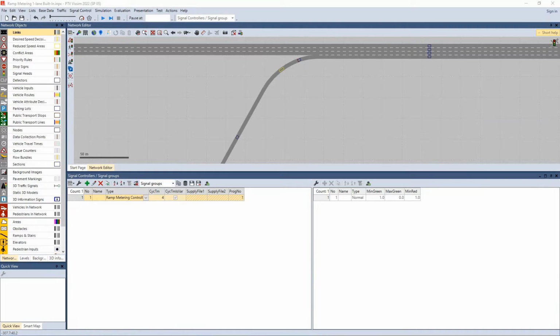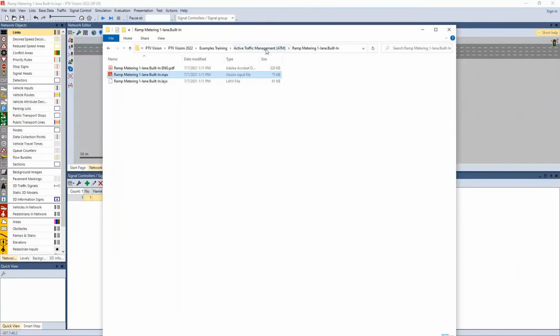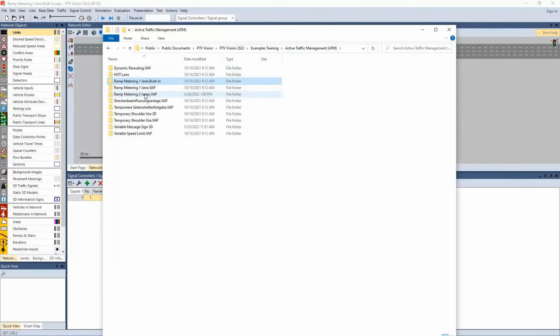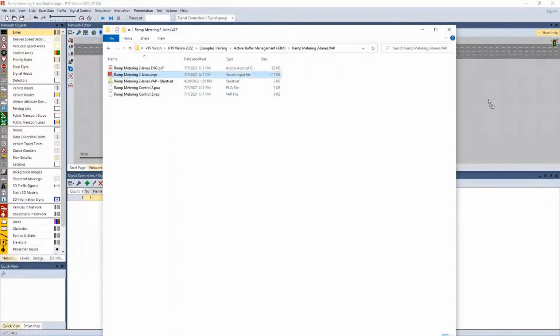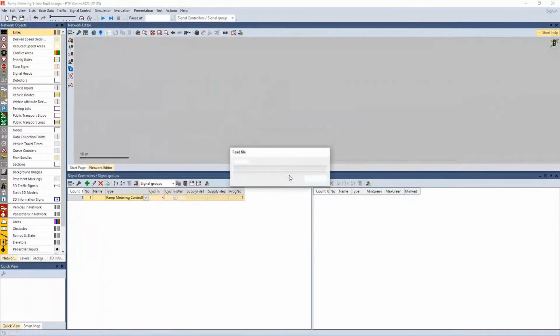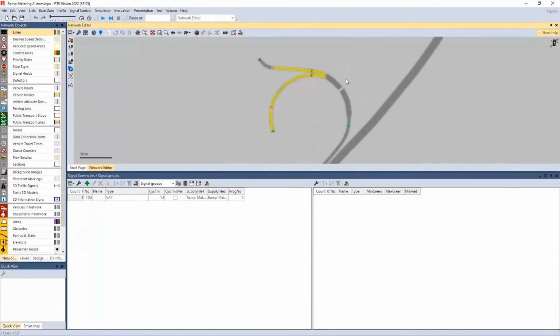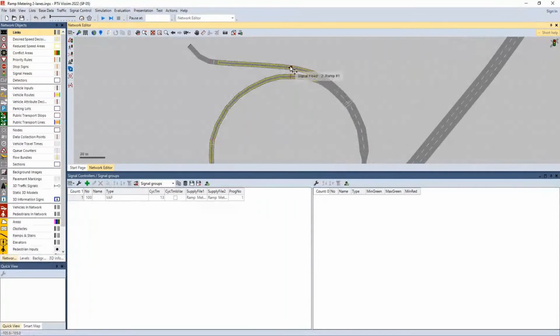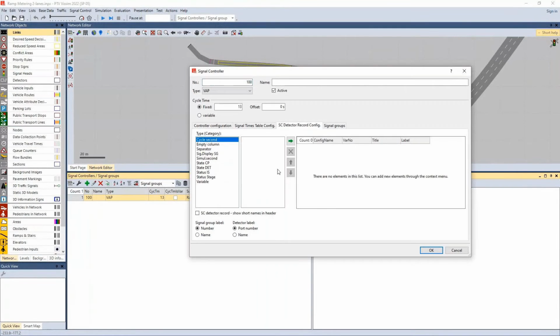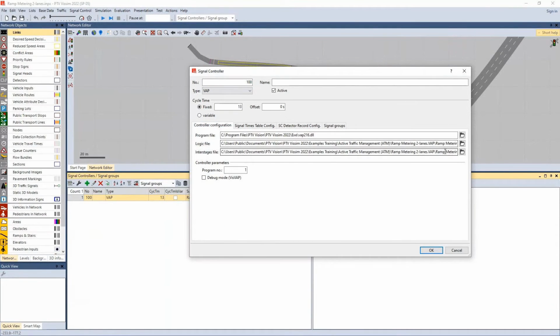If you want to have multi-lane ramp meters, you can't use that built-in one. You'll have to use a VAP controller. A VAP controller is just another type of controller. VAP stands for Vehicle Actuated Programming. In this case, we have two different phases on the same ramp meter, and a VAP controller is basically like a script-based controller.